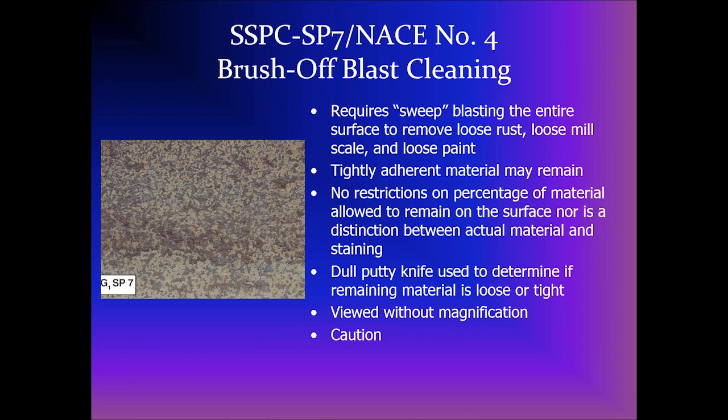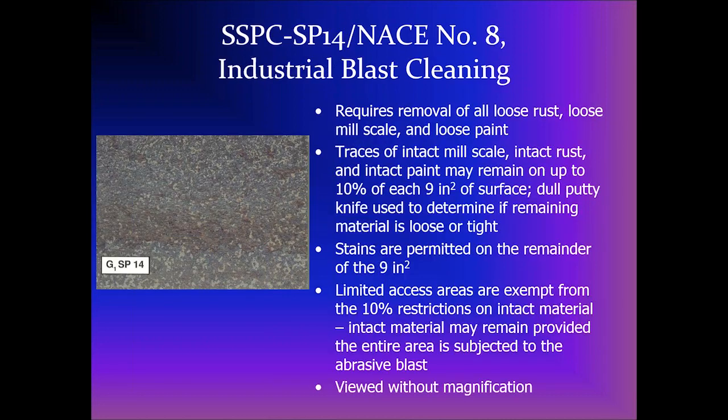There are times that a brush-off blast on an old coating has created problems by fracturing and weakening that coating, although you don't know it. You put another coat on top of it and it pulls that old coat apart in service. So brush-off blasting should be used only in the right circumstances. Make sure the surface is a suitable candidate before you specify brush-off blast cleaning.